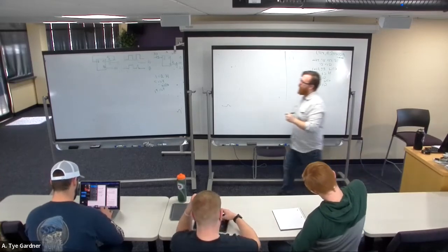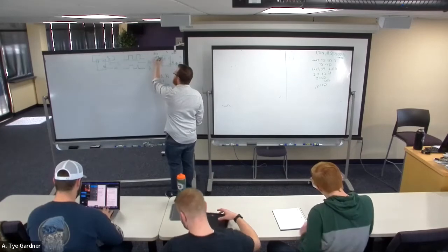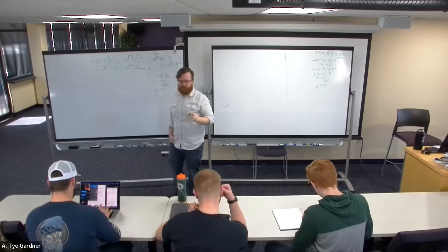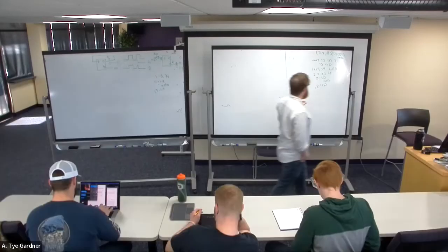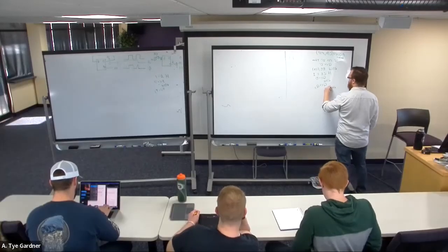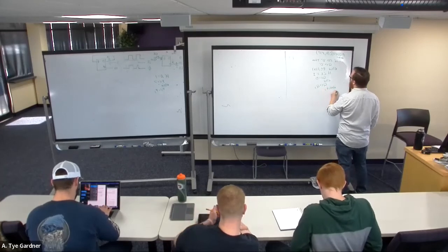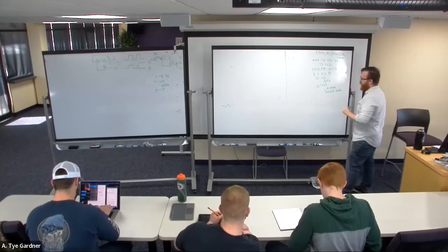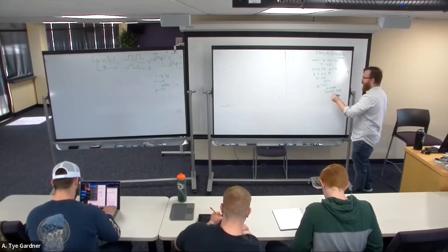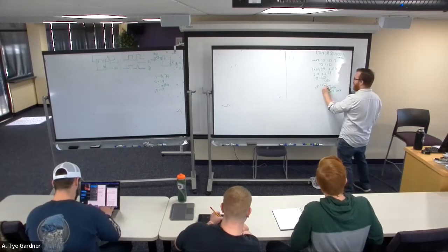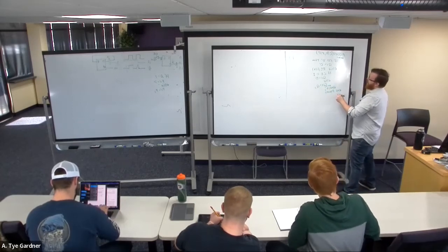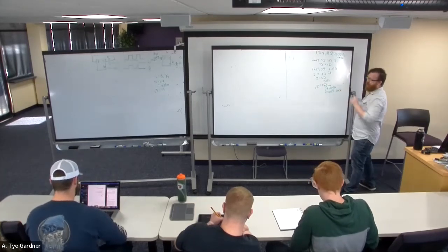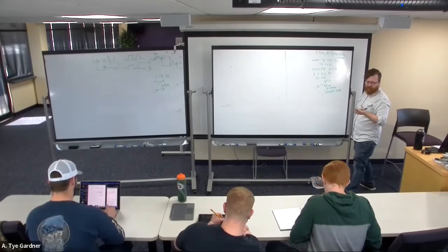Well, the way that we do that is here, this is now Q, and this is QO for my output Q, okay? I come over here, I end my if, I end my process. You have to end both ifs, I'm missing one. Okay, it's okay though, right? Here, there's another end if in there. Now I've ended the process, and now all I have to do is build the output enable device, the tri-state